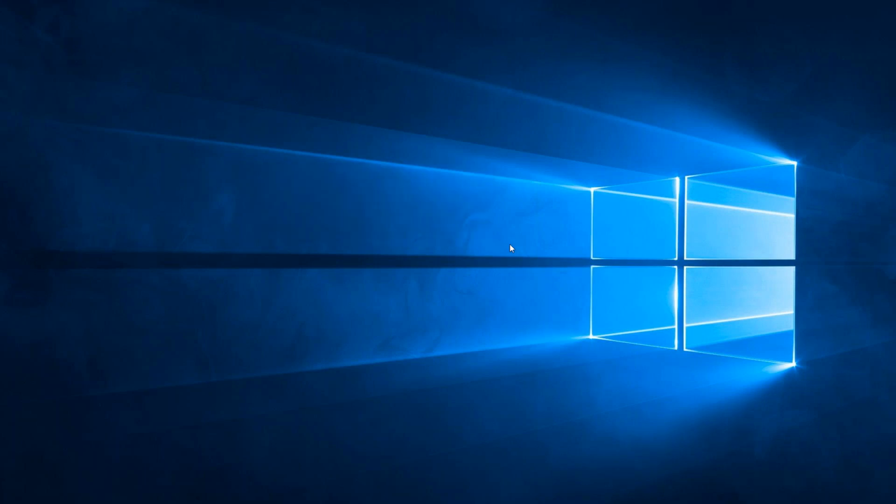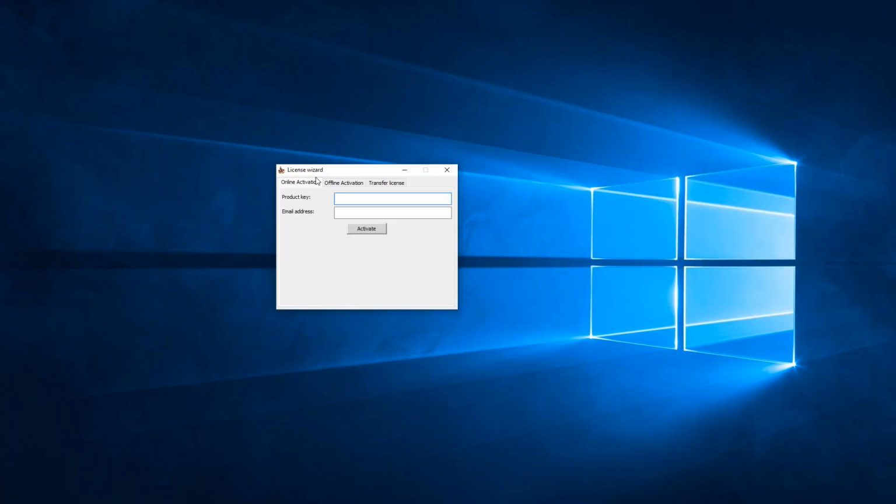And as long as that is up to date with your version of SolidCAM and you have it plugged into your computer, you can then use your SolidCAM. If you get that offline activation or even the online activation, if you're using a product key license like Kevin was just talking about, you would do the same thing. You go to your start menu, SolidCAM, in this case 2020, and then you click on the other item in that list that says software license, and then you get this window. So we have the online activation, the offline activation, and the transferring of that license.